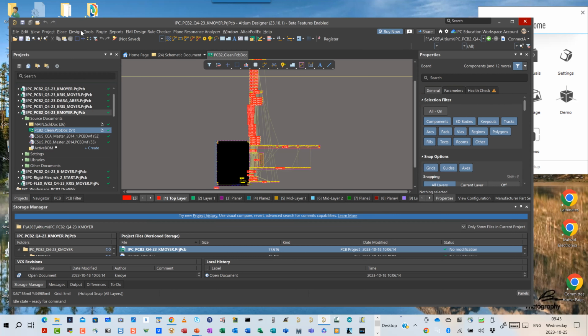These aren't like notes that go on your fab drawing, right? These are like process steps that are negotiated. It's a note outside of that. Yes and no. So we'll see this when we get to documentation, not on the fabrication drawing, but on the assembly drawing. There is an actual cleanliness designator that will say this board must be washed and I want this level of testing. I want you to test and prove that there's no surface ionic contaminants left, there's no surface insulation resistance increase or anything of that nature, and so on.